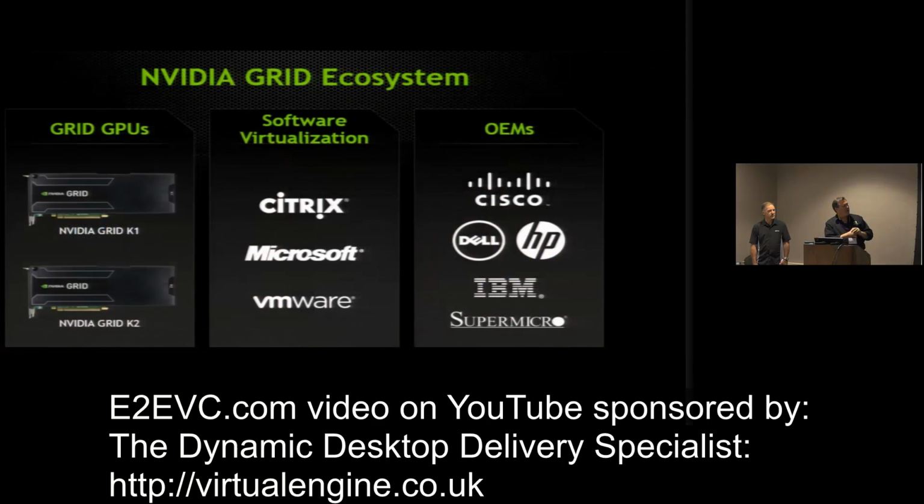So real quick, what are we offering today? We're offering 2 GRID cards today. A GRID K1, which has 4 entry-level GPUs on it. Each GPU has 4 gigabytes of dedicated frame buffer memory. Single slot card, double width though, okay? And the NVIDIA GRID K2, which has 2 very high-end GPUs, equivalent to the Kepler 5000 card that's out today, on the card. Same form factor.